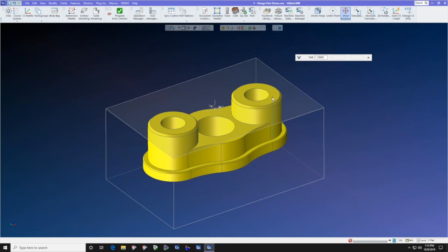If I click here, notice that a line shows up, and you can see that that line is 1 1/4 inches long. That is called the thickness indicator line. If I just click and hold my mouse, that's 3/4 thick from there to the bottom of the part. And from here to the bottom of the part, we can tell that that ledge is 1 1/4 inches tall.